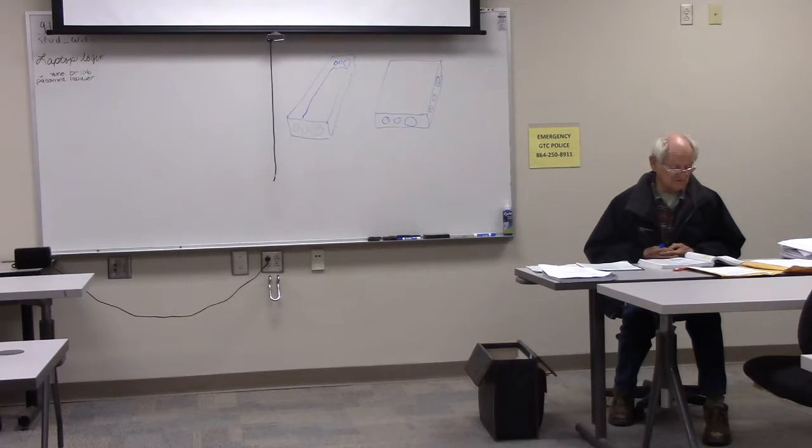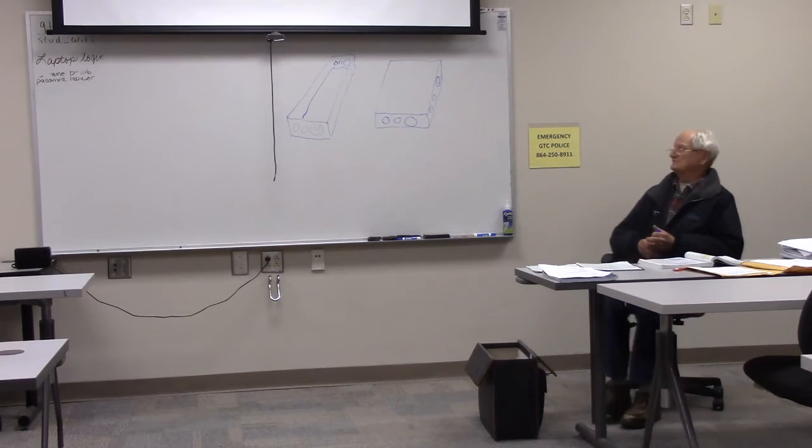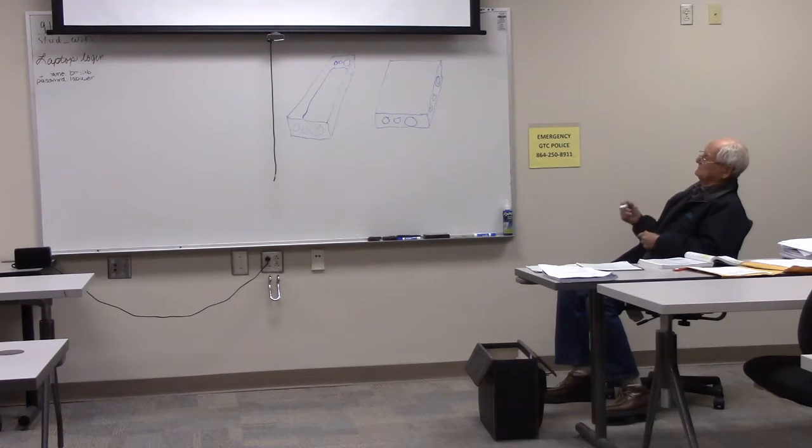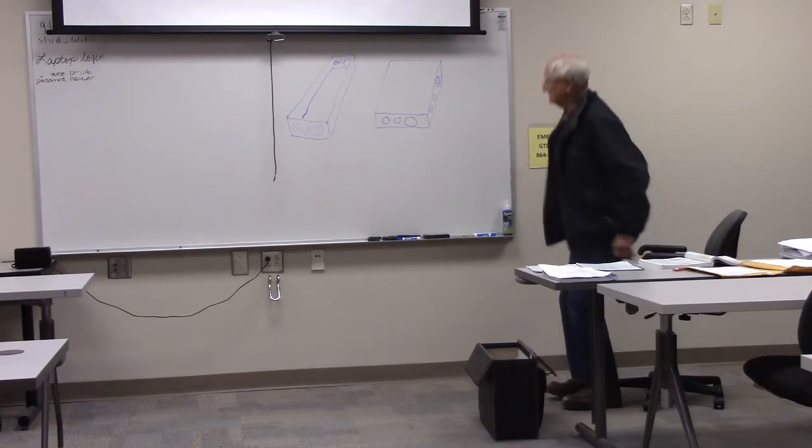And transposing cable size is the raceway size, the minimum trade size required; the number of trade sizes shall be used. All right. Installing pull and junction boxes. Pull boxes installed at convenient intervals will relieve much of the strain on the conductors. I mentioned this earlier to you.